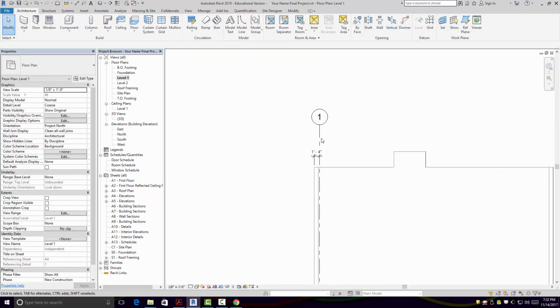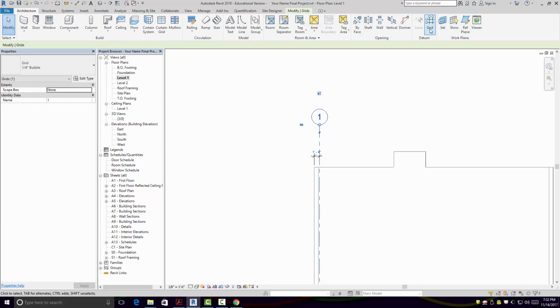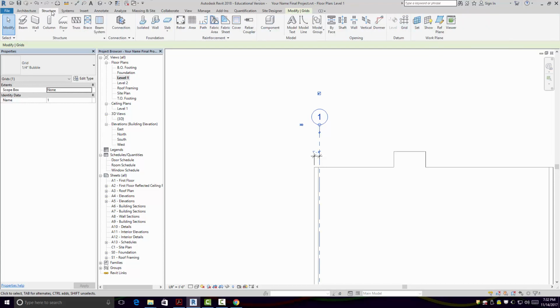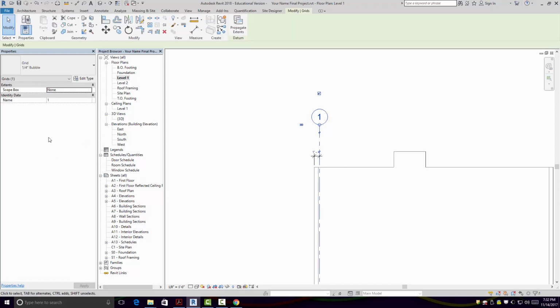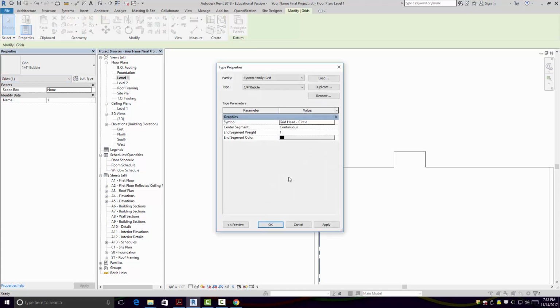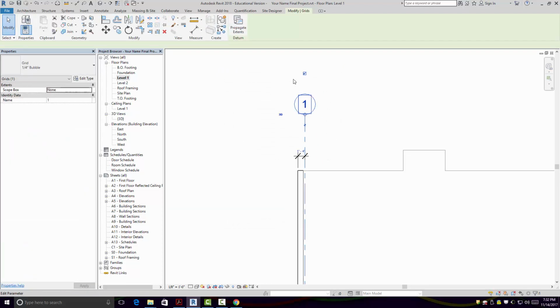Okay, so that'd be it, and then you would have multiple grids. How did I get it? I went to Architecture, and I went to Grid over here under Datum. It's also on Structure, and I started to go there first. I don't think it makes a difference, but go under Architecture. It may filter. Let me see. No, I don't see a filter. There's probably no difference between the two. They like changing stuff like that on me, but I don't see a difference.